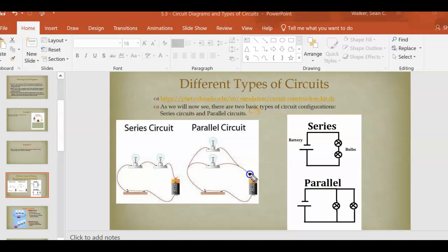In a parallel circuit, the current comes out here, and then right here it gets to what's called a junction, where the current can actually split. We've talked about wires being like pipes, and the water flowing through the pipes being like electric current. If you imagine a pipe with water flowing through it, it's possible for the pipe to split and go to two different locations. The same thing happens here with the current. The current flowing out of the cell can split at this junction, and some of the current can go that way, and some can go that way. But then the current reaches this point over here and recombines back into the original current and keeps going.